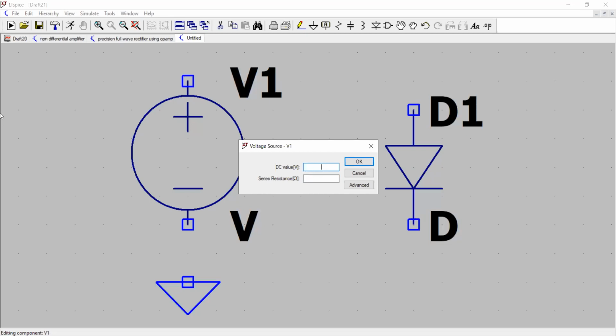So assuming that it's a silicon diode, I don't know yet if it is a germanium diode or silicon diode, what its cut-in voltage therefore is. So I will just assume, and that I want to know after I run the DC operating point analysis, or maybe sweep this DC voltage source and check the current flowing through the diode.